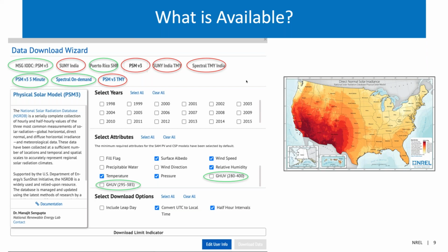And for Solar Anywhere or any of those semi-empirical models, what it is capable of is generating a GHI, and then there is another model which you have to use, the decomposition model, which then separates out DNI and diffuse, and that's based on ratios of diffuse to global. There are various models, but one of them has been developed by Dr. Richard Perez. So that's what most of the commercially available models are. That and SolarGIS use similar types of methodologies.